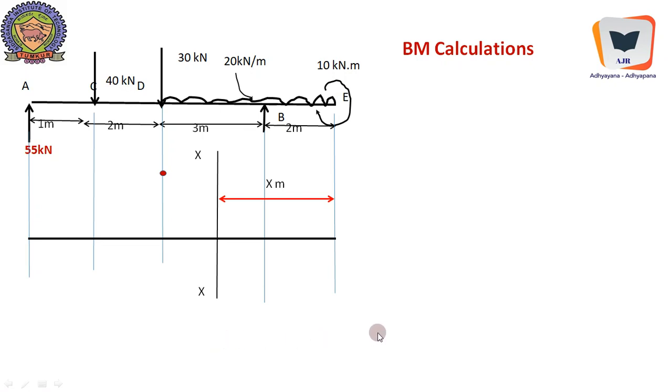Yeah, we will compute the bending moment calculations now. Bending moment at E is not equal to 0. It is a readily available moment which will rotate this point also, in a way the beam hogs. Therefore, bending moment at E equal to minus 10 kilonewton meter.